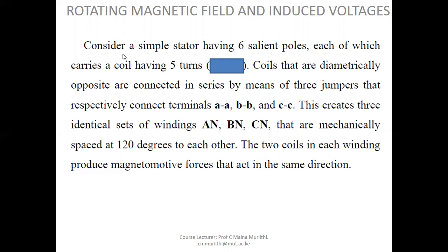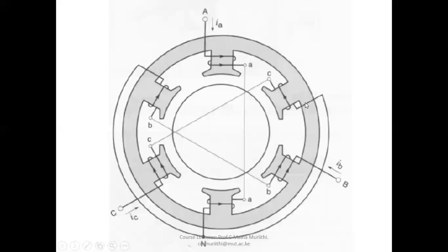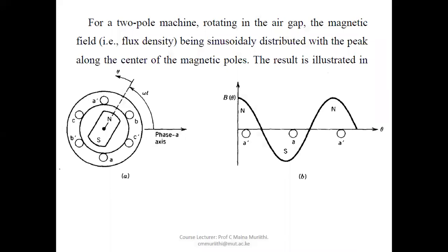Though perform some small recap. So we considered such a machine that had the three-phase windings set, and we discovered that if we allow the currents to flow as indicated, there will be a revolving magnetic field created in those three-phase windings that will revolve as indicated at an angular velocity omega. That angular velocity will later become what we know as the synchronous speed.